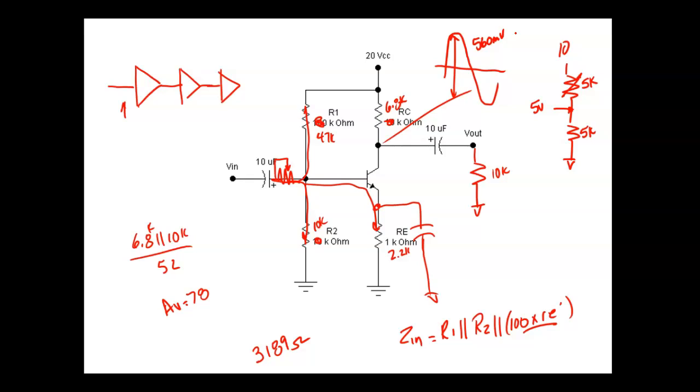As soon as I start adjusting that pot, the output is going to start dropping down. When it gets down to what? What's 1/2 of 560? 280. Is that right? When that sucker gets to 280 millivolts, I know that the resistance of that pot is equal to the resistance of the input of the amplifier when it drops down to 1/2.